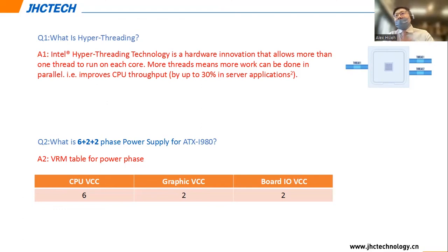Another one is for the graphics VCC, or what we call SoC PCH, for the internal graphics, not a graphics card like NVIDIA. It uses 2 phases. And for the board I/O, we use another 2 phases. So that means we can provide more stable power on the motherboard.